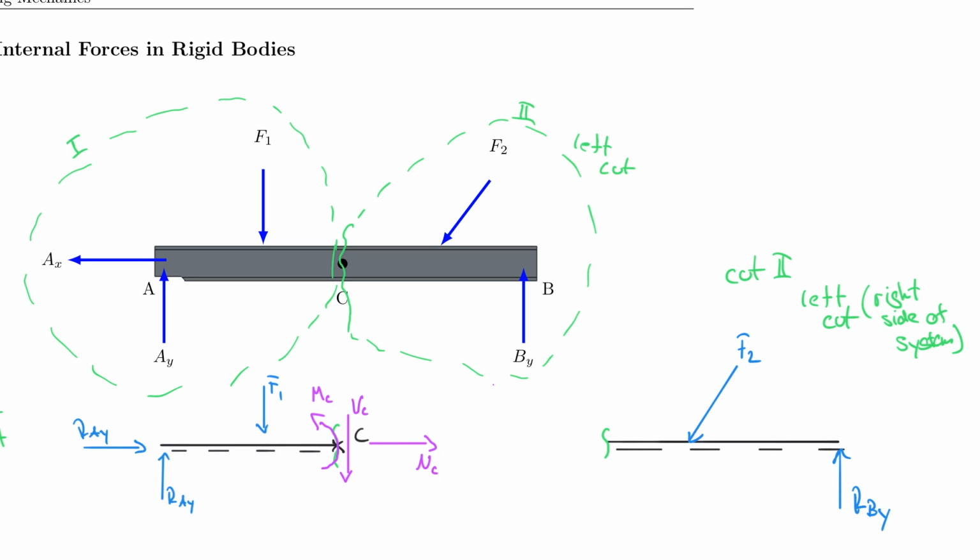So I have to bring in my external forces, which ultimately are the internal forces. But because I made the green cut there, I now actually have external forces, a vertical one, a horizontal one, and a moment, if you will. And of course, they now have to balance whatever I have defined here. So therefore, they point upwards, they point to the left, and they rotate clockwise in this case. And of course, they are also N of C, V of C, and M of C. And now the left side is in balance with the right side. This is always the case. And this is just shown conceptually here, but with numbers, this will come out to be the same, as you will see when we solve our example.